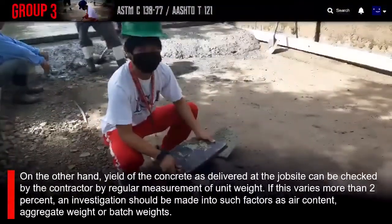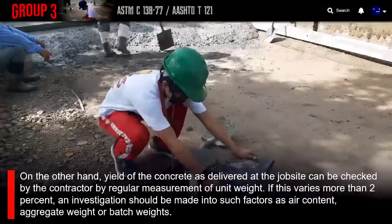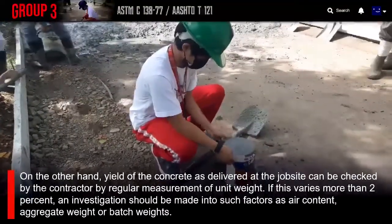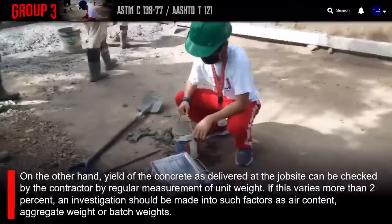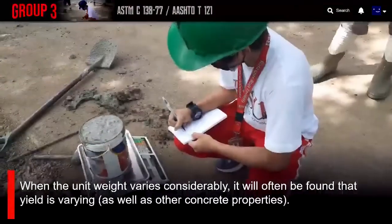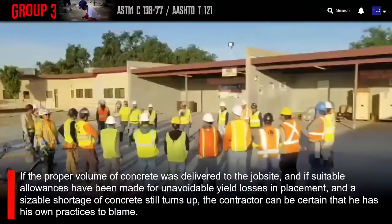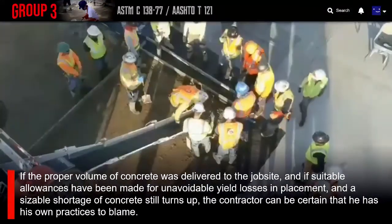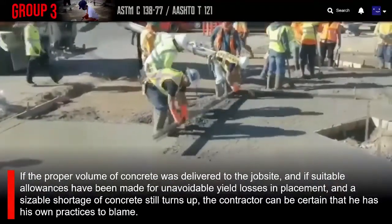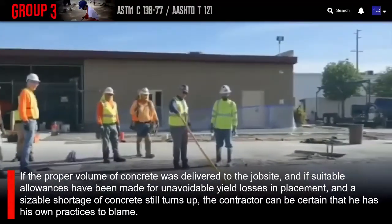On the other hand, yield of the concrete as delivered at a job site can be checked by the contractor by regular measurement of unit weight. If this varies more than 2%, an investigation should be made into such factors as air content, aggregate weight, or batch weights. When the unit weight varies considerably, it will often be found that yield is varying, as well as the other concrete properties. If the proper volume of concrete was delivered to the job site, and if suitable allowances have been made for unavoidable yield losses in placement, and a sizable shortage of concrete still turns up, the contractor can be certain that he has his own practices to blame.